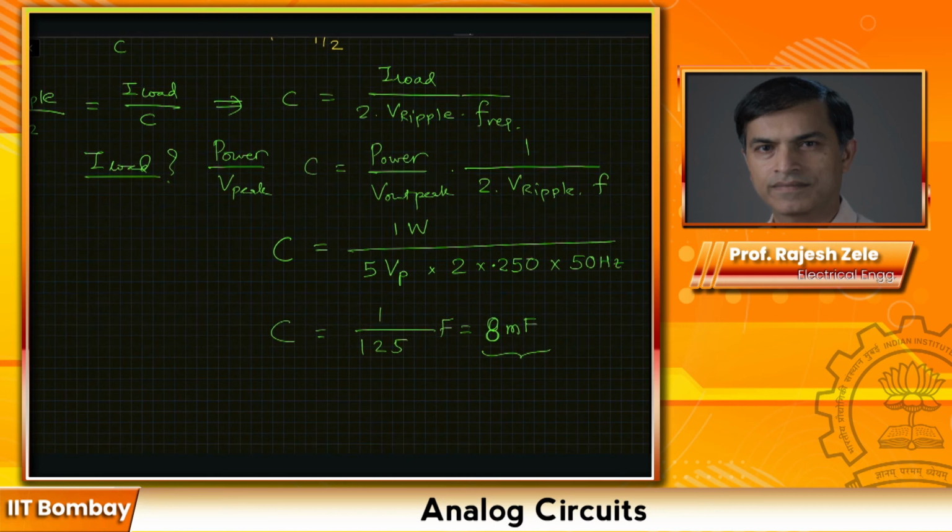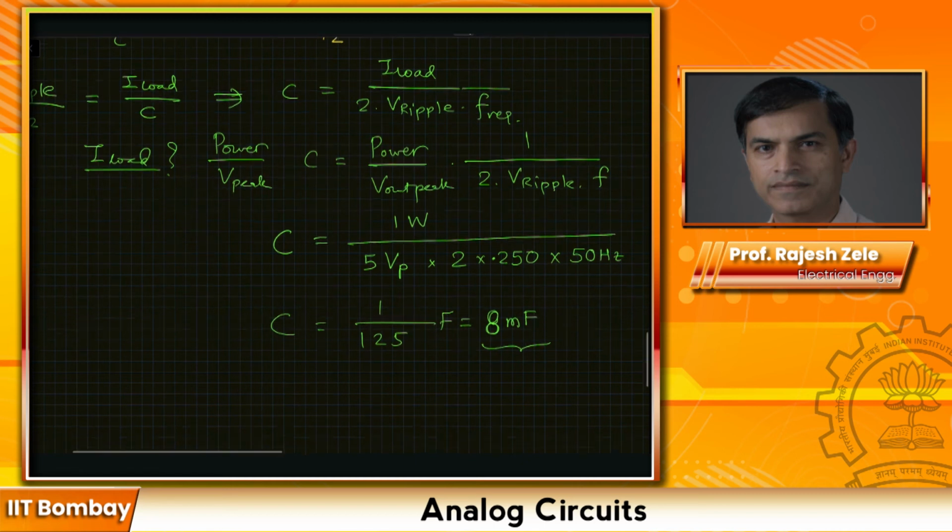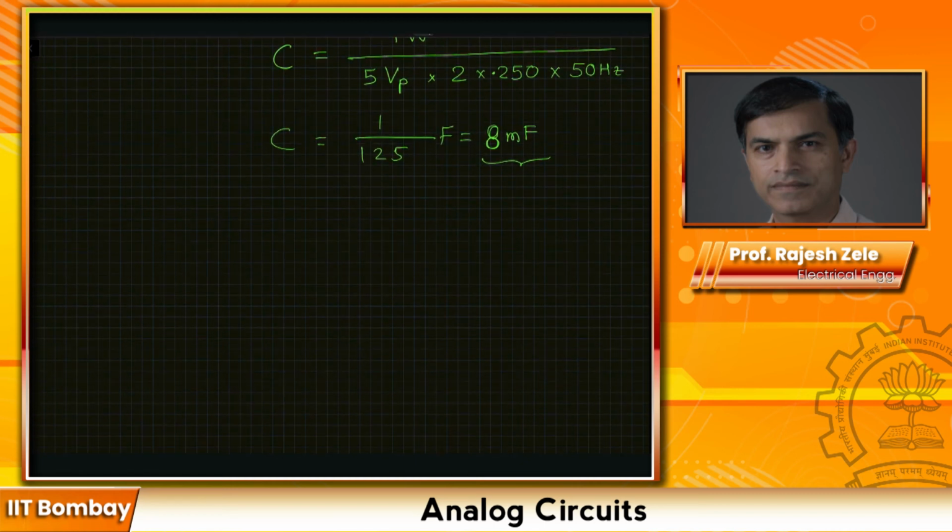But there are many circuit applications, and one of them I'm going to show to you, where the input voltages are very small. It can be millivolts, it can be tens or hundreds of millivolts. Then how do you rectify those signals? And one good example of that, which all of us use in our cell phones, is something called received signal strength indicator. Okay, so this is a little bit of a detour, but you will appreciate what this circuit does